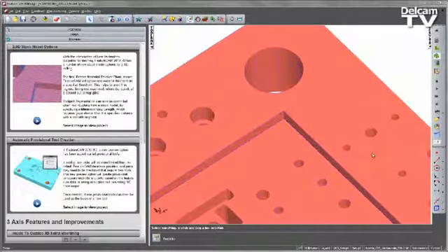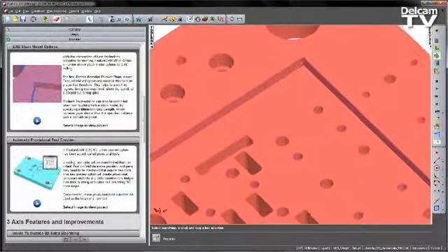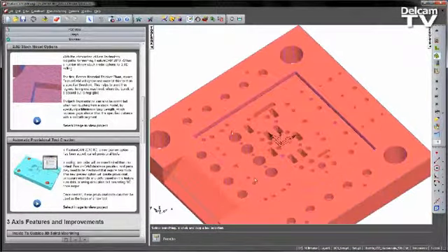Toolpath fragmentation can also be controlled when rest roughing from a stock model by specifying a minimum gap length. This replaces gaps shorter than a specified distance with a toolpath segment. Now in this particular part we can see we've got some sharp corner regions inside this pocket section.